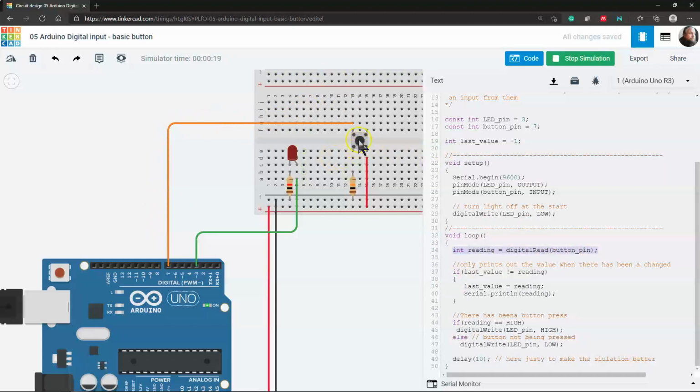So with the button not being pressed, it'll be sending a low, so it goes here, it's a low. This value shouldn't have actually changed here, and then boom, we come in here, and it's going to check here, okay, it's not high, it's low, so it's writing out a low to it, and then delaying for 10 seconds.